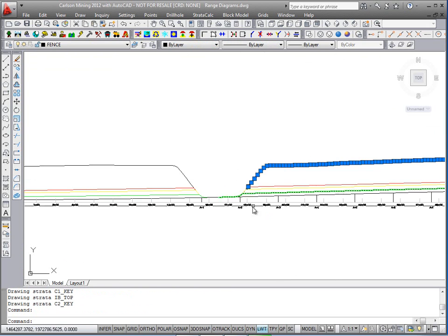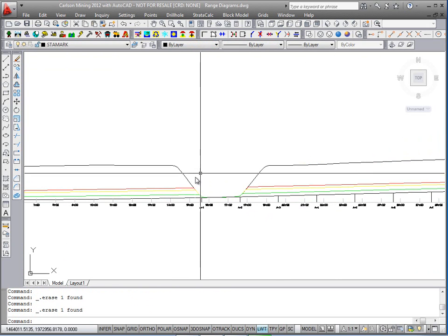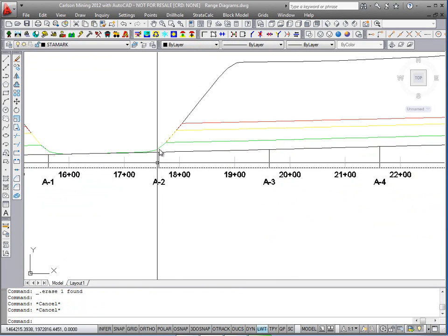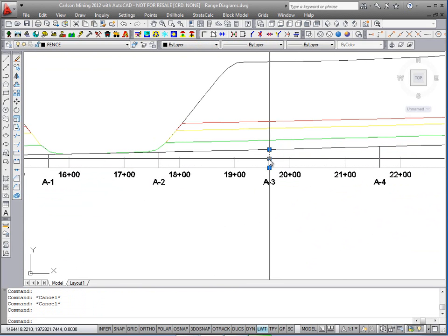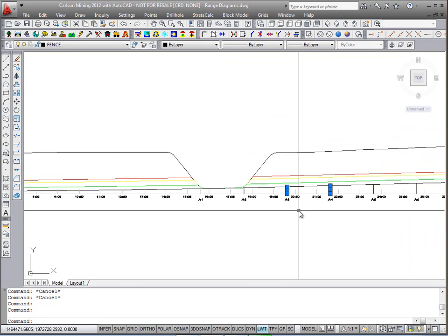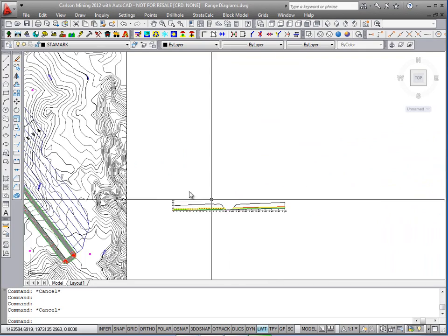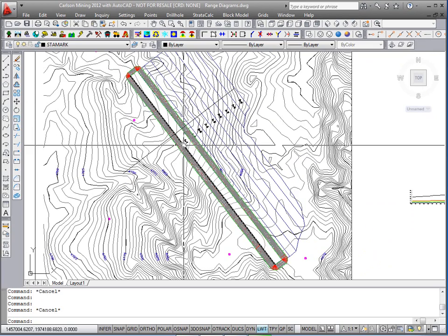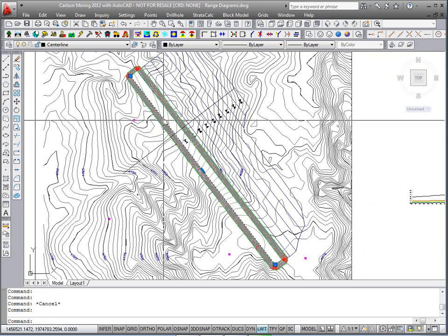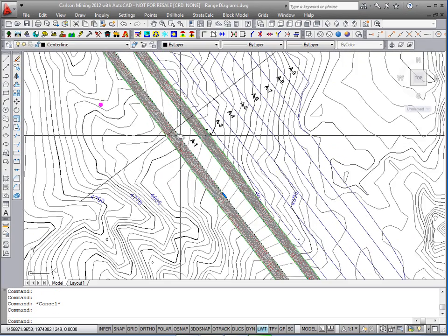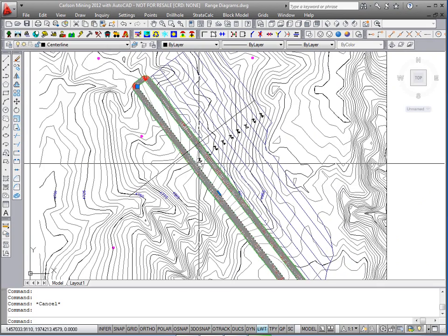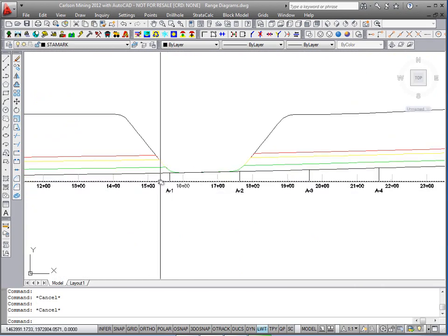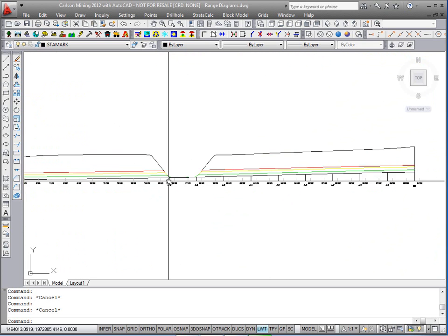You can delete these partial topo lines, and that leaves then the continuous ground surface line. There you can see the pit lines are drawn up to the bottom of the strata. Our center line, when we go to 3D, we'll need to process it down, up and down a center line, and that's this polyline that crosses the cross section right at the front or the beginning of pit A1. And so that center line reference point is right there.